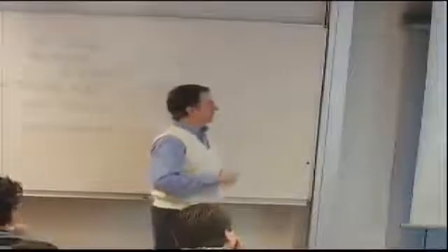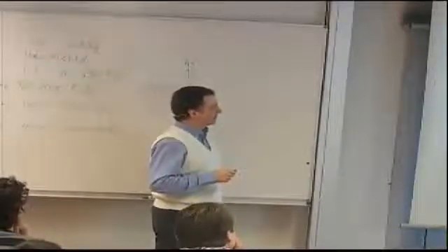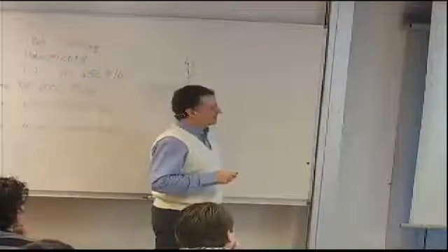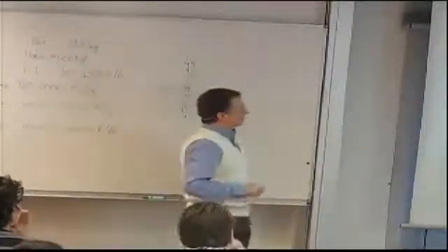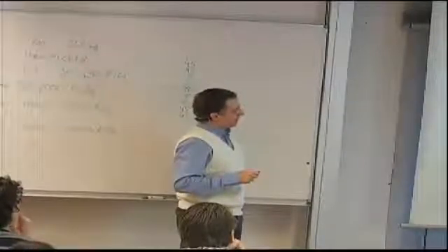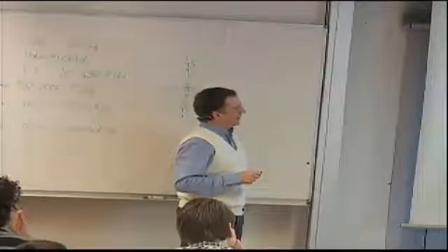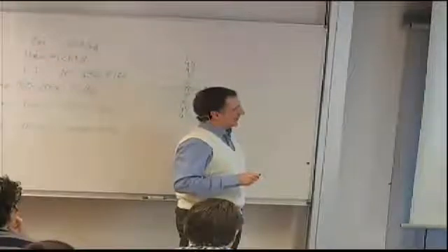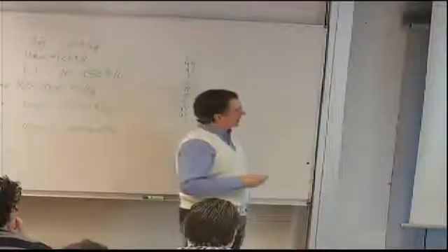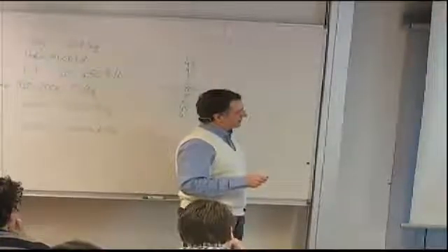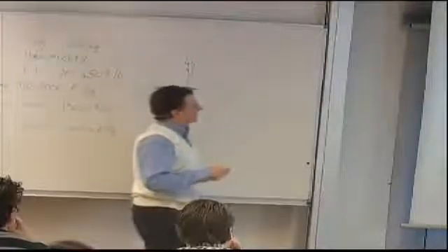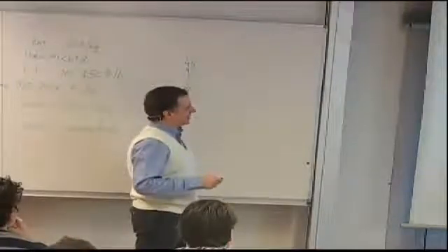So if we do an example, and suppose I have some kind of a planar application, the weight, or the mass, I guess, I usually call it weight, officially it's the mass, is density times the thickness times the area, the planar area of that structure. So if I have failure, I know that the failure stress will equal my applied load divided by the cross-sectional area, width times thickness. So I can solve for this thickness, which is my applied force divided by the width times the failure strength.